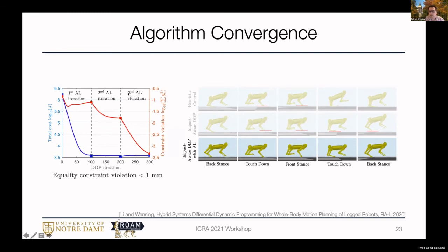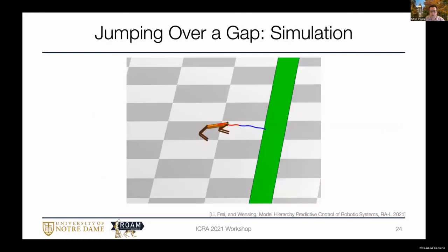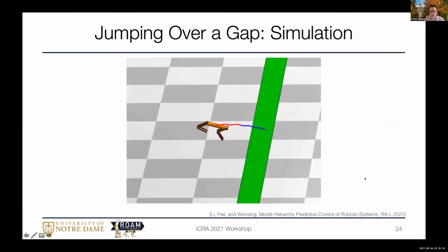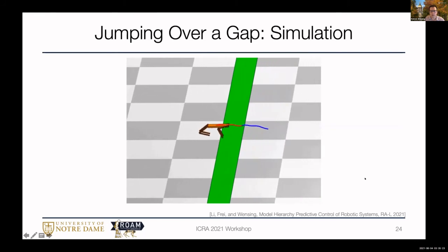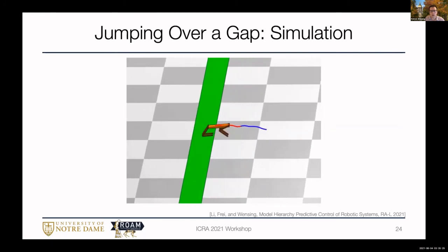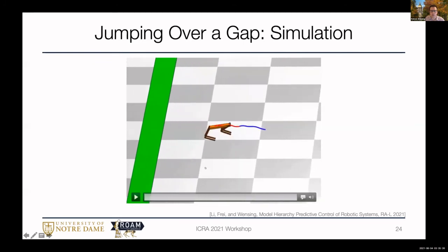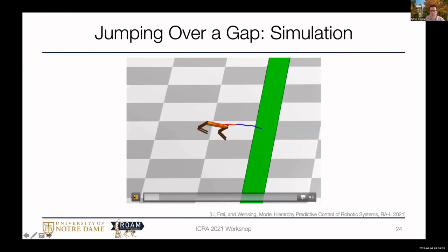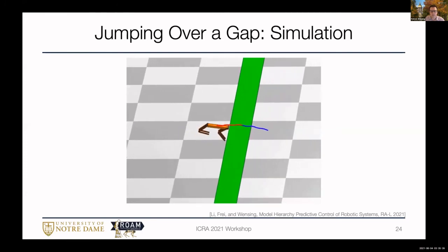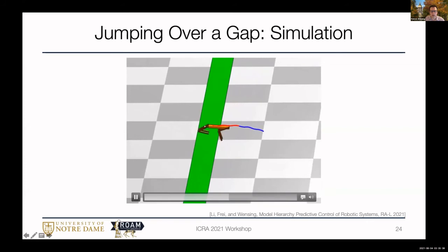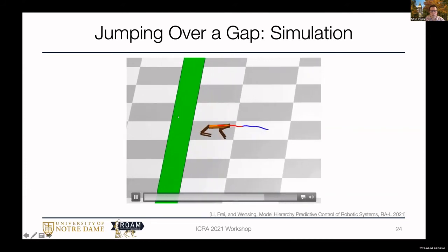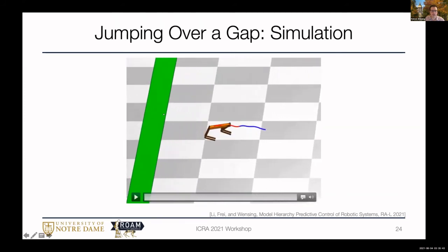So we've been looking at using this in my lab to enable the mini cheetah robot that we have to handle more challenging scenarios. So here's a video from one of our simulations doing some real-time MPC in the sim. And so you'll see here what we're doing is we're solving this trajectory optimization problem in a receding horizon fashion, always updating it as we go. And so here, this green area is an area not to step. You might think of it, green is like a garden that you don't want to step on or something of the sort.